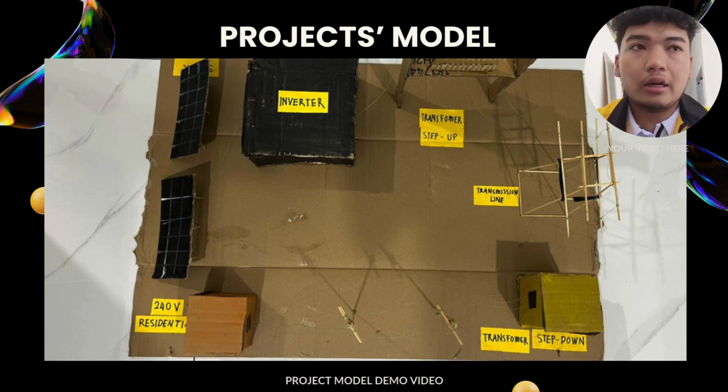The third is the step-up transformer for voltage increase. The AC then enters the step-up transformer. The transformer increases the voltage level. Higher voltage is used to reduce current and minimize power loss during transmission. This stage represents the preparation for long distance transmission.